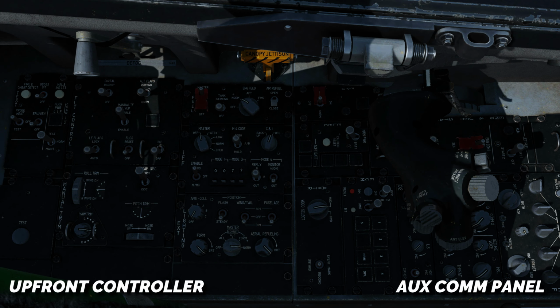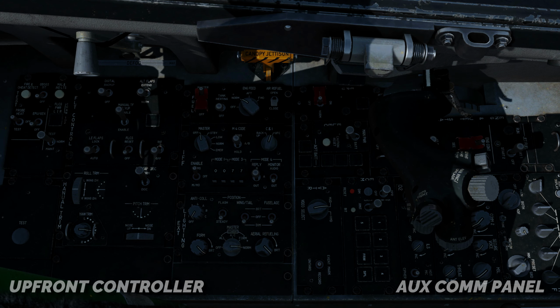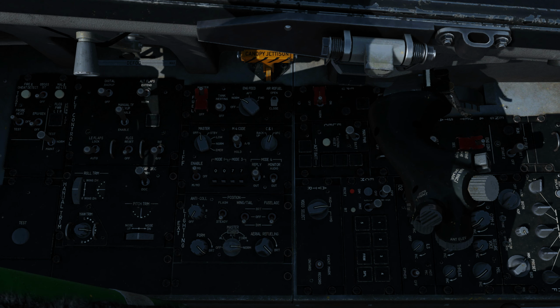The UFC requires main generator power. To provide alternate operation of UHF, TACAN, and IFF, set the Communications Navigation IFF knob to backup.